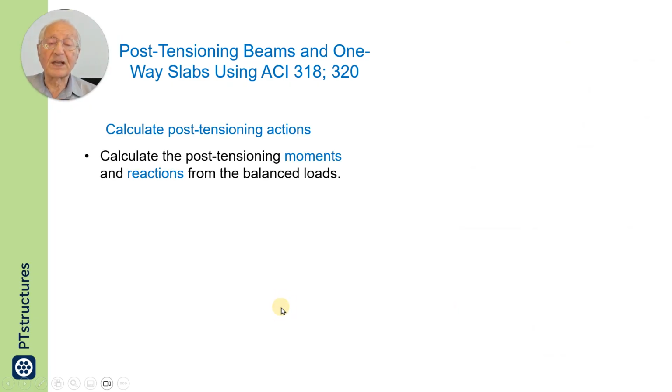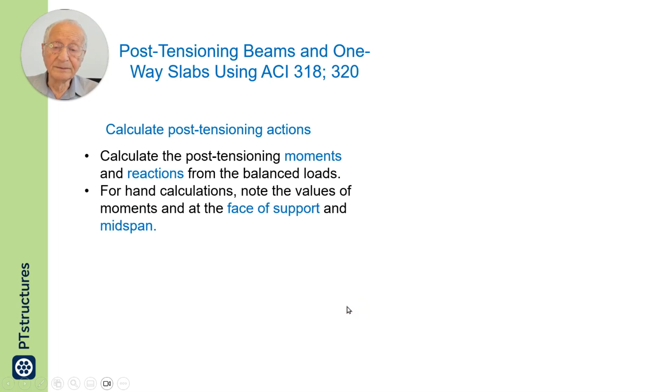Calculate the post-tensioning actions now. We calculate the post-tensioning moments and reactions by applying the balance load that I showed at the bottom right of the previous slide to the member.